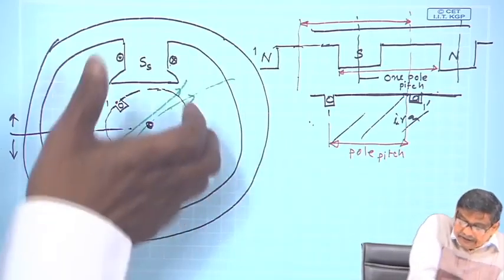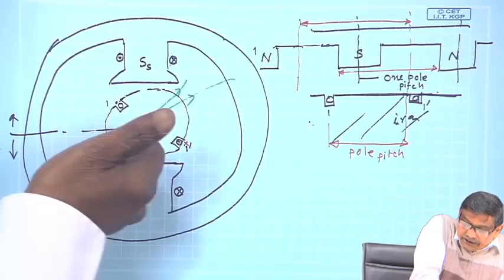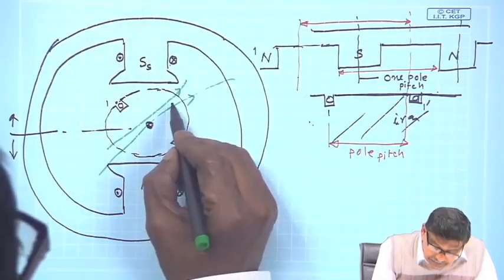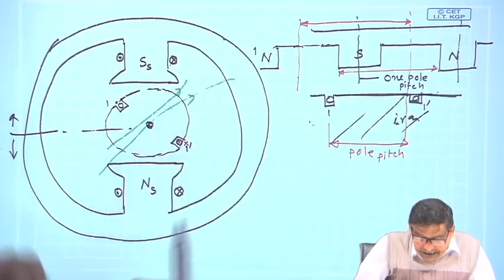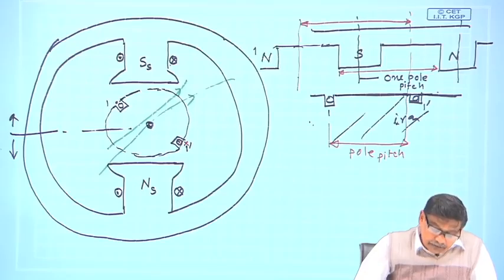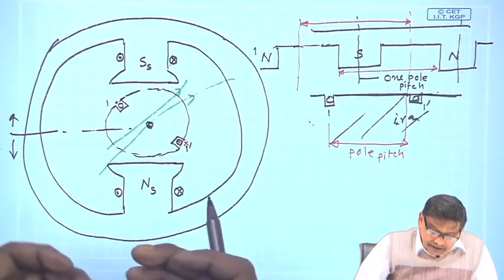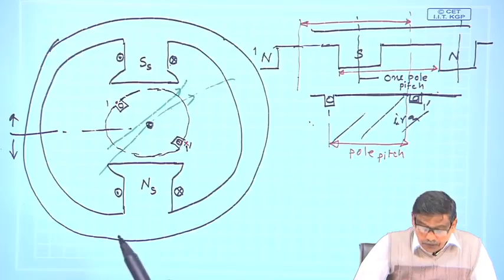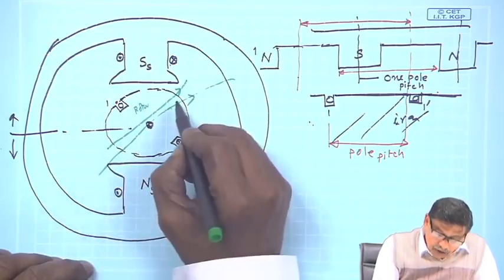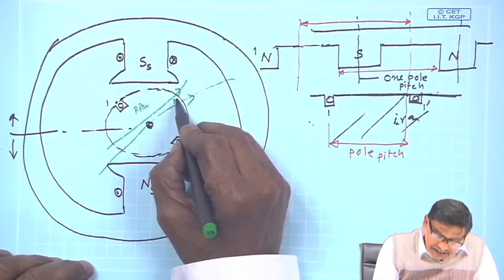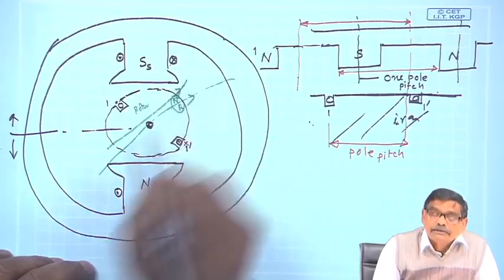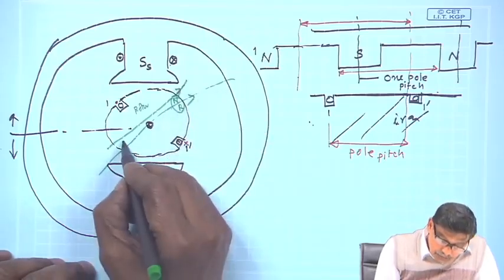Is not? This is the rule, cross this way. So, this will produce a field, and if it produces a field, therefore, the rotor carrying current ultimately produces a magnetic field. And if I ask you where is NR, where is SR, the south pole of the rotor, this is the rotor, the north pole must be here, I must say this is NR. Why? Because lines of force are emanating from it, and the south pole will be there.